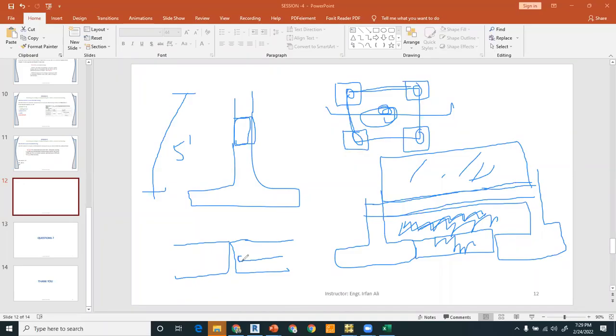So if the hook is not possible, for example, the thickness is 12 inches and you cannot provide the hook, or with some reason the development length is not fulfilling, then obviously you have to combine the footing to fulfill the development length requirement. When it is a straight bar, there will be no development requirement in here, but when it comes to the edge, you have to provide a 90-degree hook, or it will be a 180-degree hook requirement, right? So in general, you have to fulfill all the development length requirements as per ACI code. I hope this question is clear.